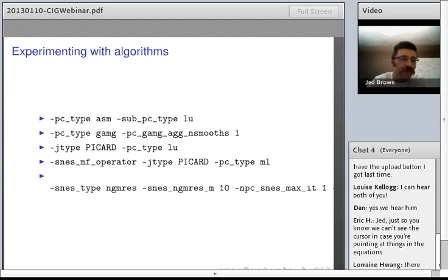So if we choose a Picard linearization, we can then do, say, a direct solver. We'll look at how that converges, and we'll see that it doesn't converge quadratically. It'll converge linearly. As an alternative, we can do this SNESMF operator. That's going to mean that we apply the action of the Jacobian matrix-free using finite differencing. This requires nothing more than the residual evaluation.